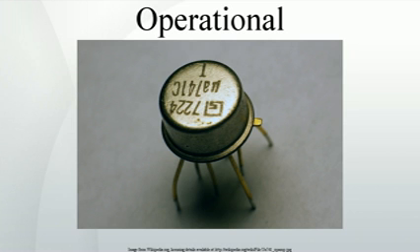Inverting amplifier. In an inverting amplifier, the output voltage changes in an opposite direction to the input voltage. As with the non-inverting amplifier, we start with the gain equation of the op-amp. This time, V is a function of both Vout and Vin due to the voltage divider formed by RF and RIN. Again, the op-amp input does not apply an appreciable load, so substituting this into the gain equation and solving for the gain, if A is very large, this simplifies. A resistor is often inserted between the non-inverting input and ground, so both inputs see similar resistances, reducing the input offset voltage due to different voltage drops due to bias current, and may reduce distortion in some op-amps.